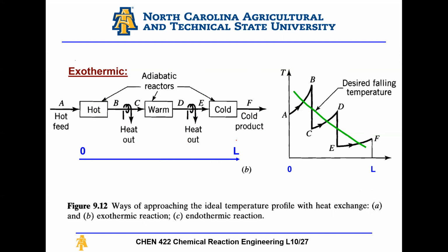Anyways, you need this system when it's difficult to introduce the required heat exchange within the reactor. That's why we use it a lot with gas phase systems, because the heat capacity of gases is much lower. So if I have a huge volume of reactor, it will make it very hard to cool down the entire reactor effectively. Whereas if I have 3 smaller reactors, I can always affect this heat exchange better on a smaller gas volume.